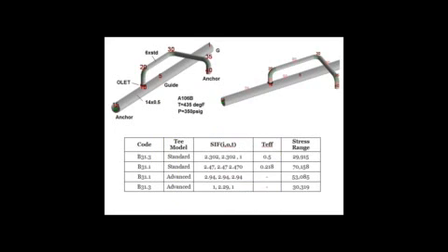Now the interesting thing that affected this was the details of the supports. And the details of the supports are something that a good analyst needs to take a look at. And FEA tools isn't going to help you with that. You've got to have a good experienced designer put the supports in the right place for that system to keep the pump loads reasonable and to build them properly.